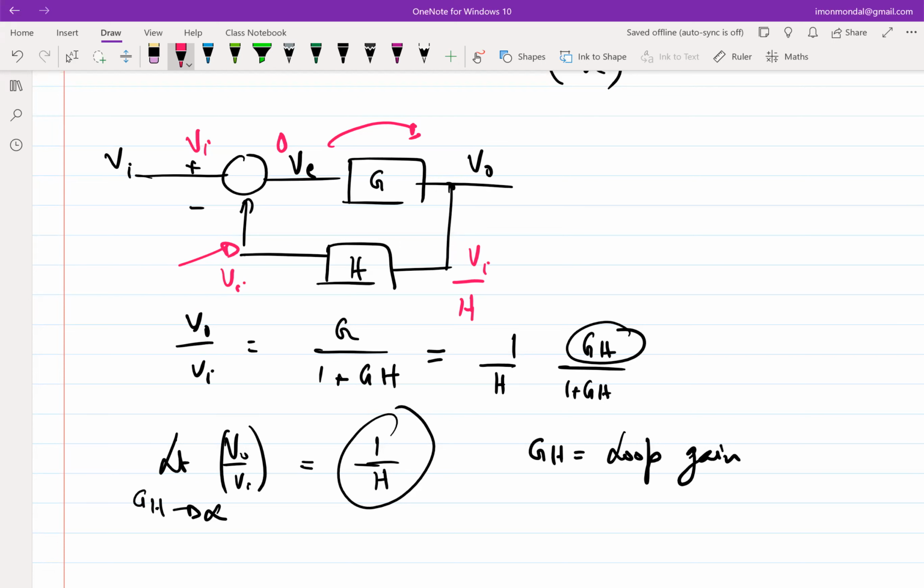But the issue is when you are dealing with infinity, when you are saying the loop gain is infinity, a limiting value of infinity times something which goes to 0 can also be finite. So you cannot precisely find out what V naught is if the forward transfer function is infinity and you also go in the forward direction. So a negative feedback loop is always best analyzed in the reverse direction. You go backwards, you never walk forwards.